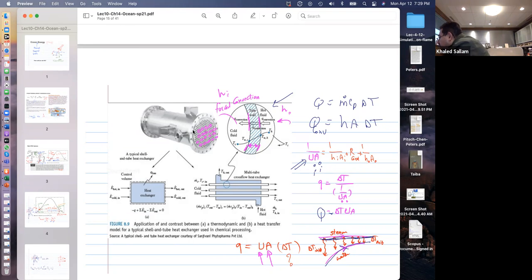So each one of those configurations or flow regimes, whether it's forced convection or internal convection, they have formulas for them depending on, say, the Reynolds number, how quickly the flow is moving. It'll tell you in this range, use this. In this range, use this. Also, it could be different for different geometry. So natural convection, for example, if it's a hot plate facing up, that's one heat transfer equation. If it's a hot plate facing down, that's another equation, right? But that's what this book is for.